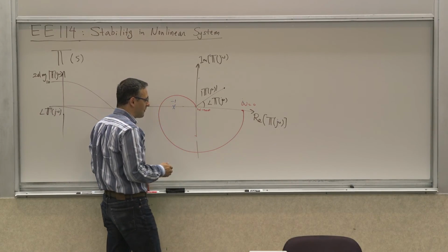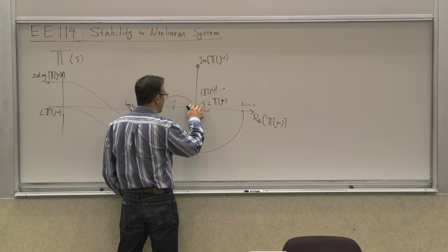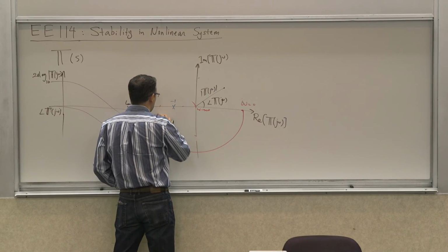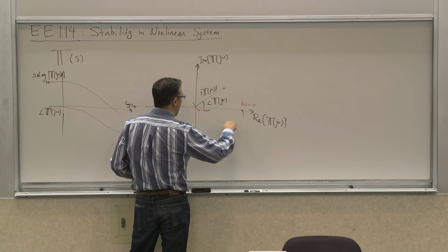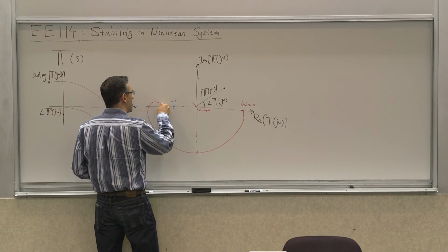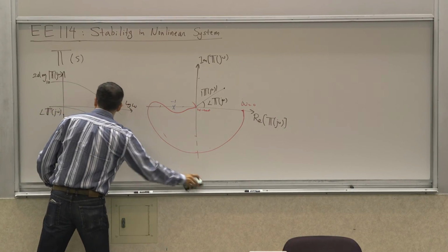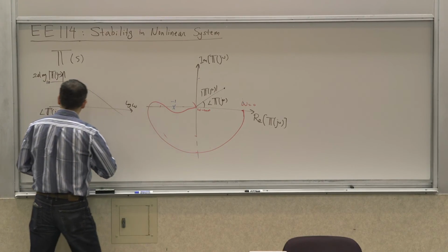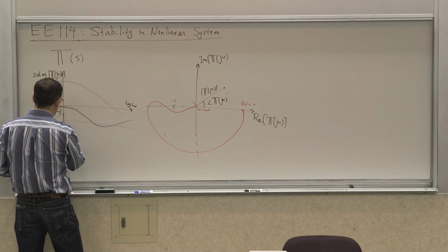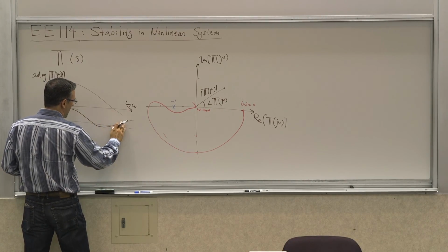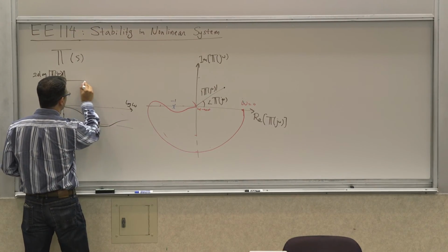Now, this was interesting, and there was another case. So the first one obviously was stable. The second is unstable, the system. And then the third, which is the interesting case, and we saw this last time too, was the conditionally stable systems, where you start from here, and you go there, and then you come back, for example, like that. And that corresponds in the Bode plot to a phase response that looks like this. And we have seen circuit examples of those too, where you go below negative 180 degrees, and then you come back up before you hit the unity gain in the magnitude.